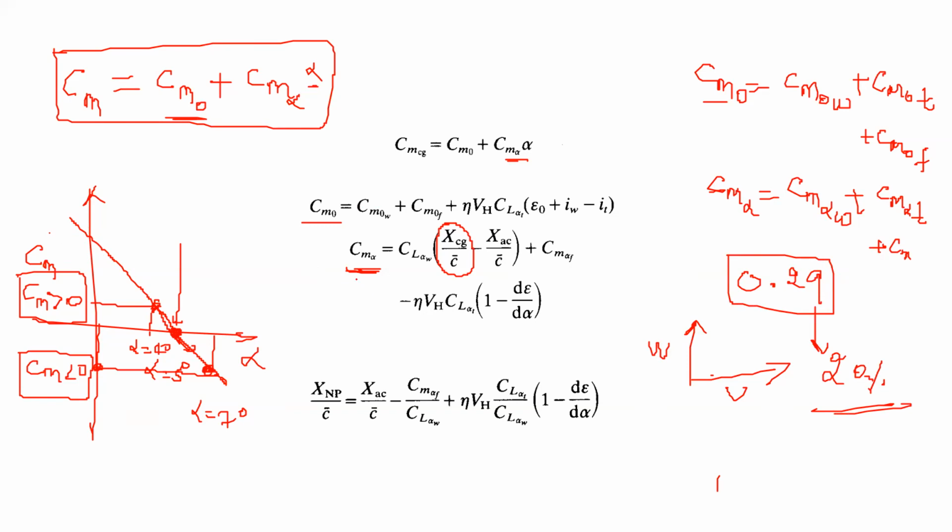Since this slope is going to change, the slope will look like this. So you have to pitch it to probably a higher angle of attack, and let's say there is a slight change of angle of attack, then your aircraft will pitch up from here, but the rate of pitching up will be slower than it was in the previous case. All right, your aircraft is going to pitch up in this second case also. This is case 2, this is case 1.